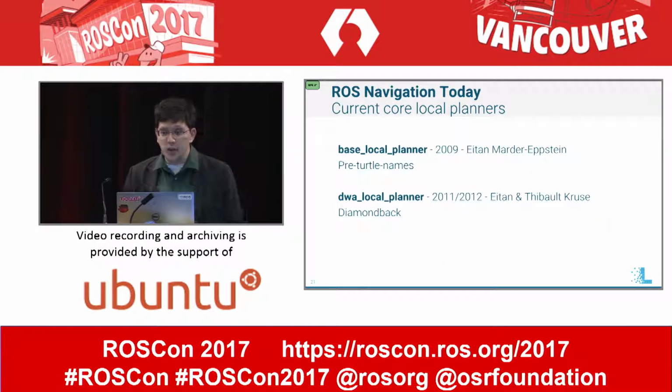So we have the base local planner that was written in 2009 for Willow Garage's initial navigation milestones. It's so long ago that it doesn't have a turtle name associated with it. And then we have the DWA local planner, which was in 2011/2012, and that came out officially in the ROS navigation stack with Diamondback. And what I talked about in the first part of this talk is exactly what the DWA local planner does. But it's lacking in a couple of particular ways.